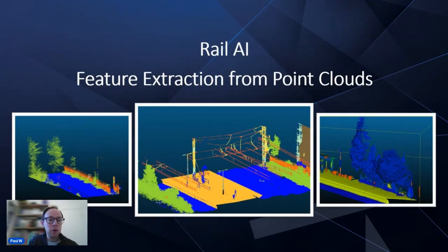Beginning with point cloud feature extraction. Feature extraction is the ability to identify, classify, and extract physical features from data. Specifically for Atlas, this relates to extracting features from visual data formats such as LiDAR and video. Where such data sets are geographically referenced, it allows for accurate extraction of feature positions and geometry, meaning they can be used in combination with other data such as design models to carry out comparison and analysis.